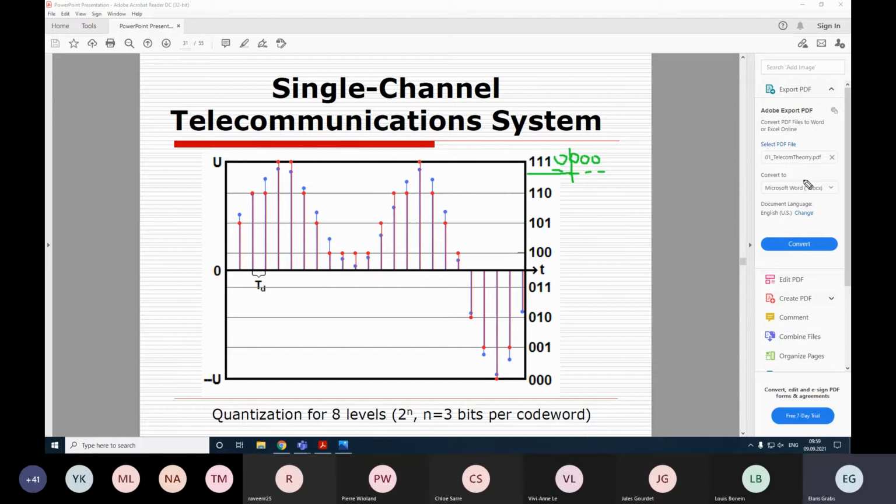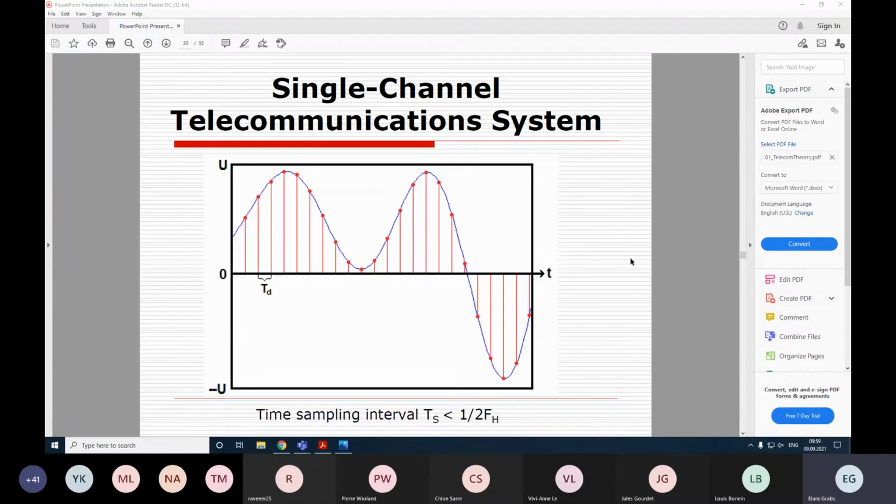So this needs to be chosen per application. In some cases you need, for example, 8 bits per level. In some cases you need 24. This can be best shown for audio. There is a standard for telephone calls, for digital communications, where we use a sampling frequency, f sampling, which is 8,000 Hertz.